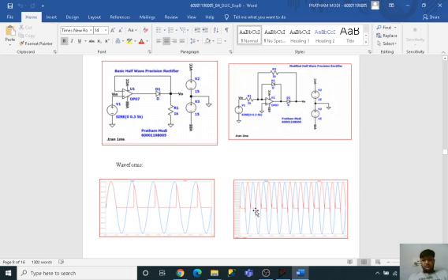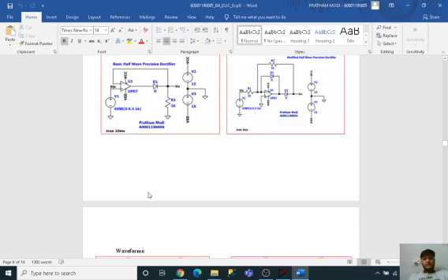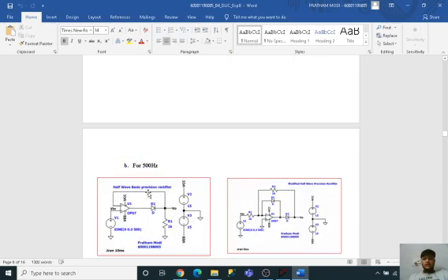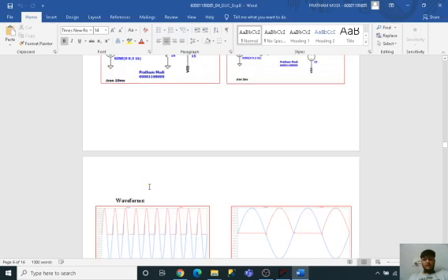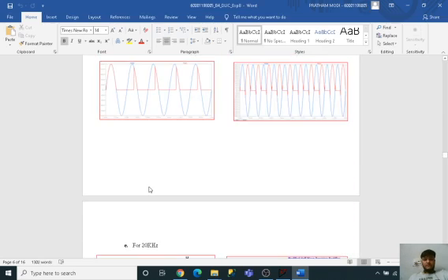There's a bit of disturbance and noise generation over here, distorted. But if we modify the half wave precision rectifier by using one more diode, then we can see a proper sine wave. It's not like we will be getting the spikes there. So at low frequencies it's not easy to see the basic difference, but as we increase the frequency we can see the differences.